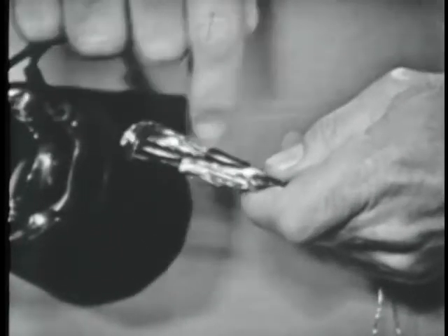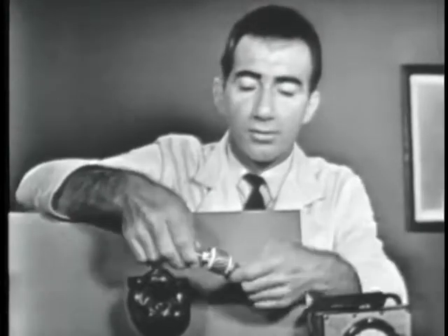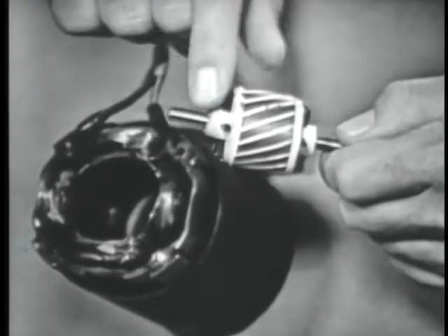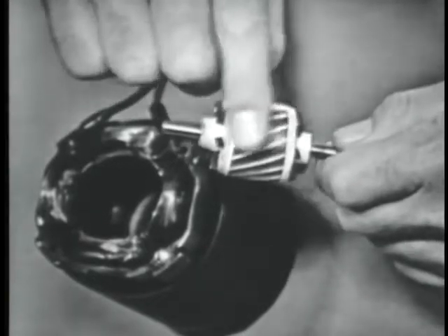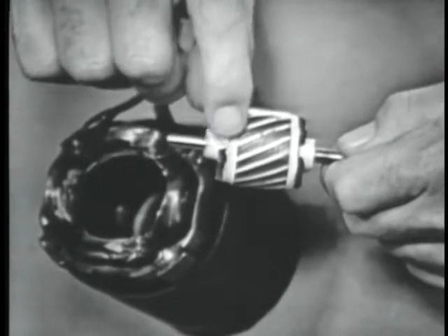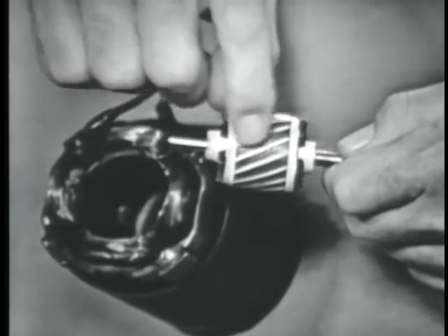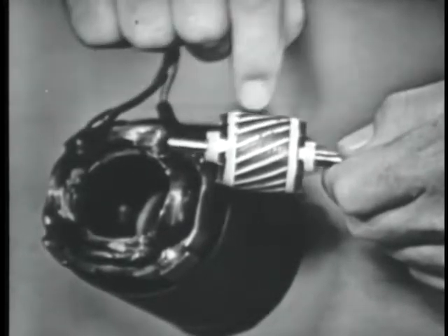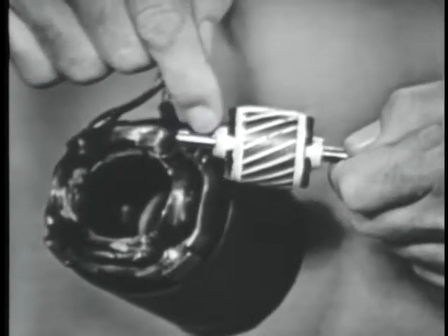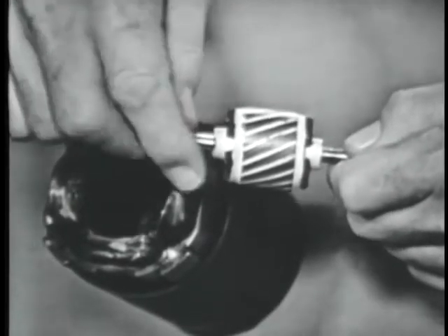An electromagnet, right. Now actually, the rotor is the same thing, or almost the same thing. And a rotor is made in a very, very similar way. Instead of using windings of wire, however, we use a conducting ring on this end, a conducting ring on this end, and they're joined together by conducting bars, these little white lines. And the reason I say conducting, sometimes they're made of copper, sometimes aluminum. This one happens to be aluminum.